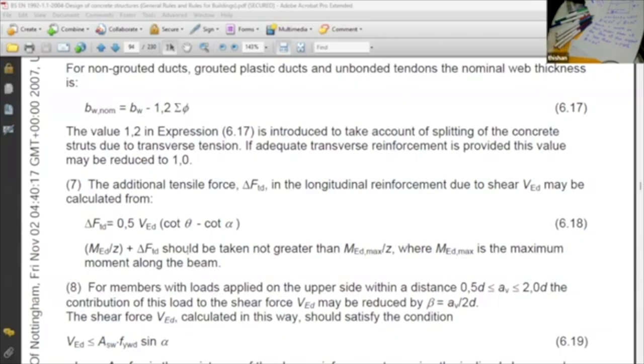Why? If you have the smaller bars as hanger bars, you can't satisfy this condition. So to satisfy this condition, you have to put the larger bars as hanger bars, the outer bars. The inner bars can be disconnected. Have you got the point, Banduka? Yes, sir. Very clear.